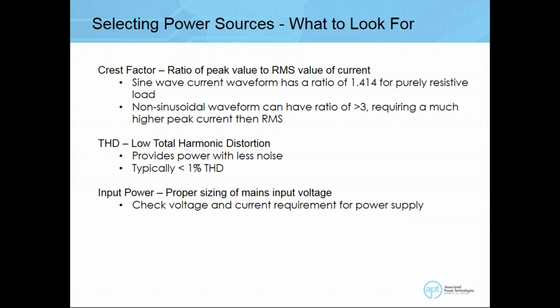And the last thing you want to check is the input configuration. There's a lot of confusion about how the power source needs to be powered up. Recently, we dealt with a customer who was confused about how the power source is going to power up, plus deliver this additional output. So you want to make sure that input specifications are noted down, and there's enough available power to power up these power supplies.